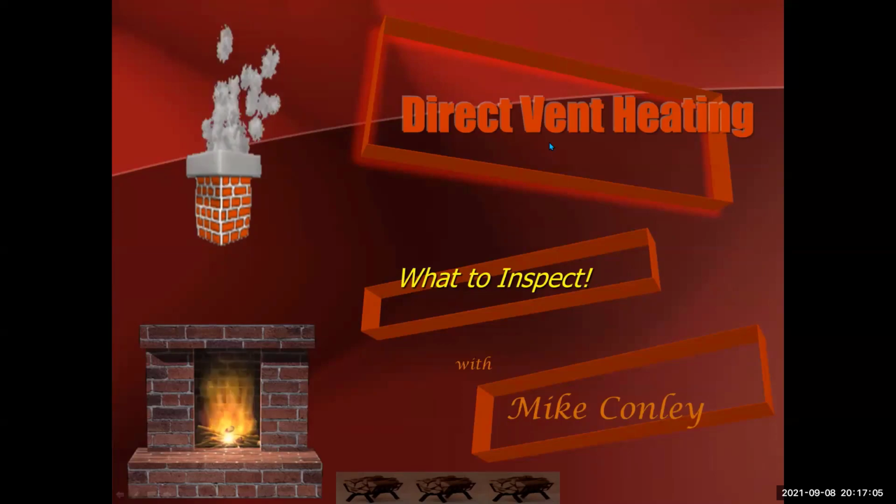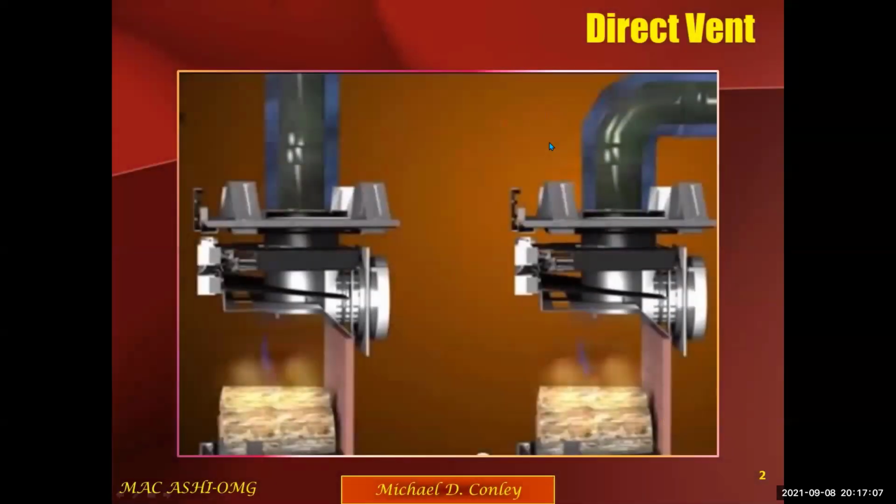So anyway, let's get started. Direct venting is venting that has a direct access either through the roof via the attic or through an exterior wall, where you can get rid of products of combustion from burning whatever it is you're burning, and have fresh air, or what they call combustion air, come back in to where the fire is located. That's basically what direct venting is and does.